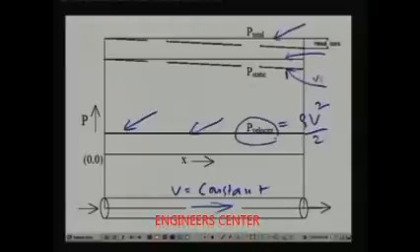Then what happens to the static pressure? Static pressure continuously reduces in the direction of flow because of the viscous effects. That means there is a loss of static head due to viscosity. So you see the sloped dashed line for viscous flow.